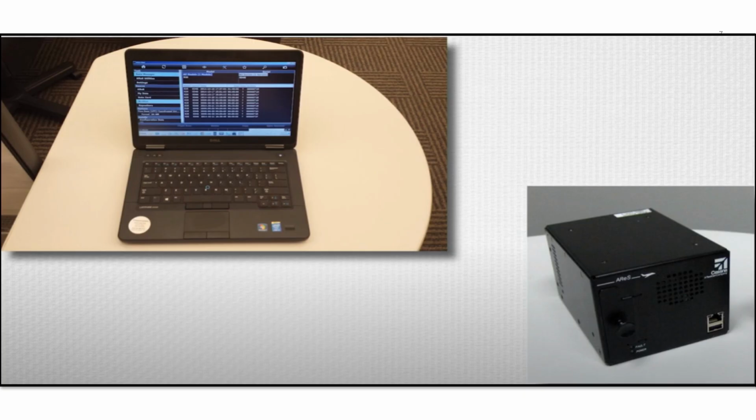Many operators choose to designate an older laptop computer as an AReS computer and configure it, including installing the AReS driver for accessing AReS, and then store it in or near the aircraft. The owners and technicians only use the laptop for AReS data analysis so that it is always configured and ready for use. The aircraft will need to be powered on with the aircraft battery, and an alternate power source such as a ground power unit or auxiliary power unit is recommended as necessary.